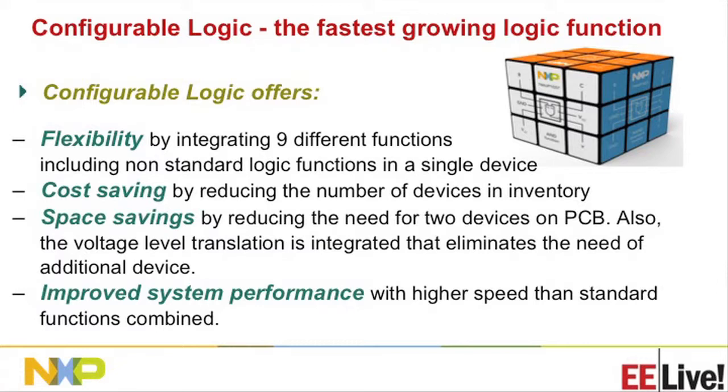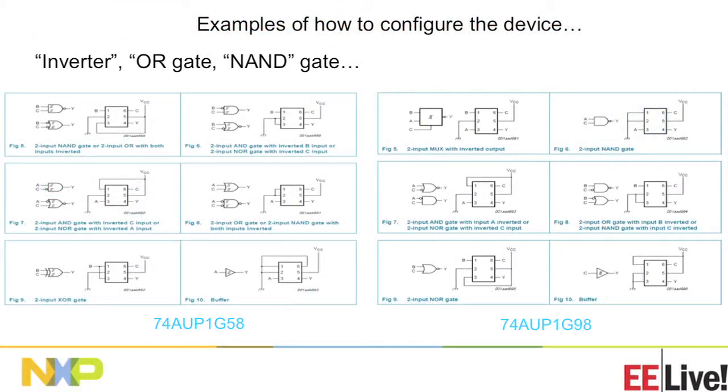And then there's improved system performance, because when we connect these gates inside the package, there's an improvement on electrical properties like propagation delay, etc. So this is how you would configure them on the board. Let's just pick 2 examples.